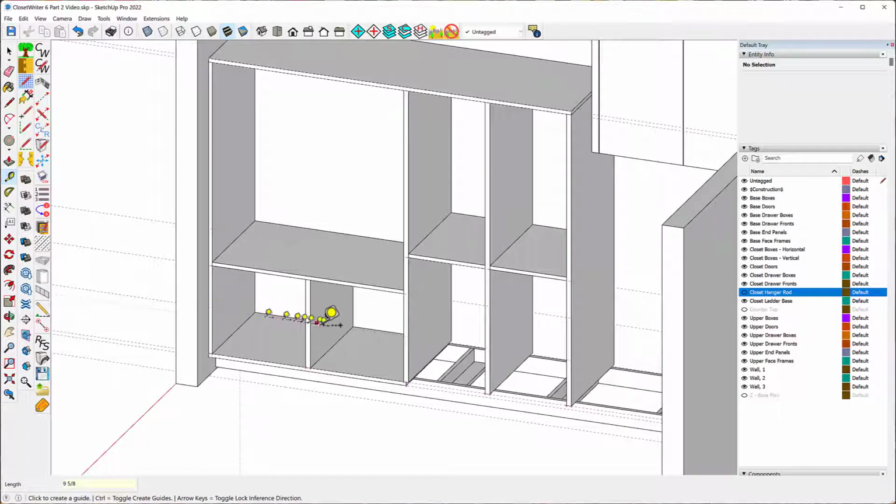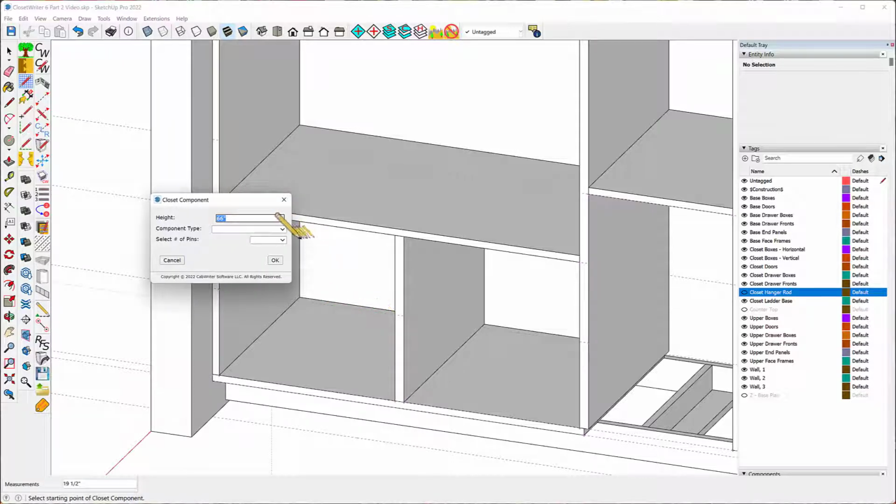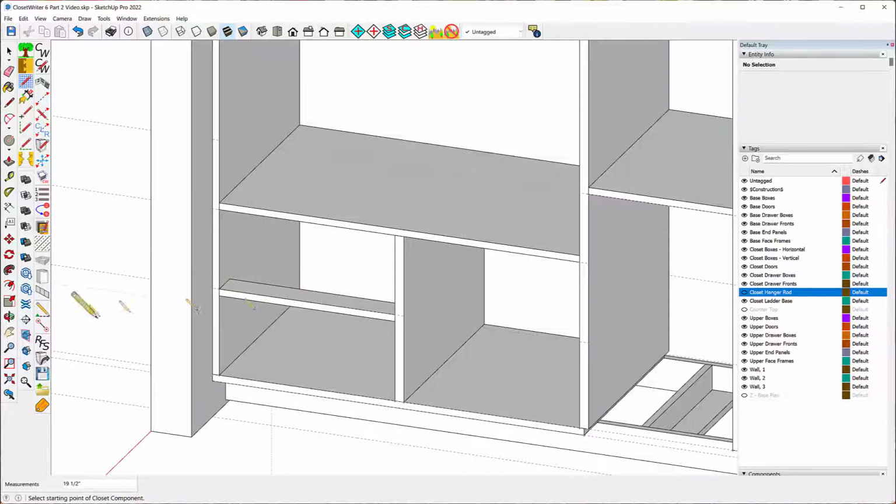And I'm going to put stretchers in here. Now remember, stretchers extrude downward. Now if I did that correctly, that opening is 8 7/8. That opening is 8 7/8. So I have one more to put in over here.